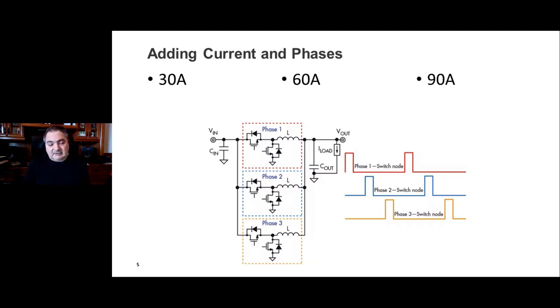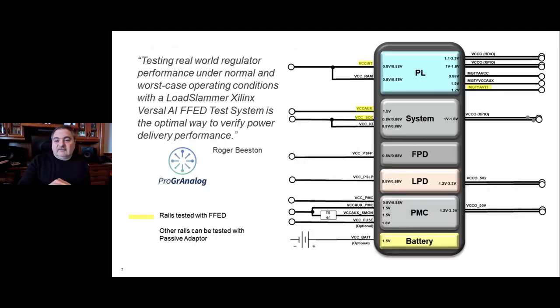Especially with non-linearities in these multi-phase solutions, as every vendor who makes a power management solution has their own proprietary architecture. These architectures are very sophisticated. They have a lot of firmware, hysteresis, non-linearities, and time constants. In the really sophisticated ones, they have mini processors in there running the firmware and the opcode. So there's a lot of potential for non-linearities to creep into the solution, and we need to test these non-linearities.